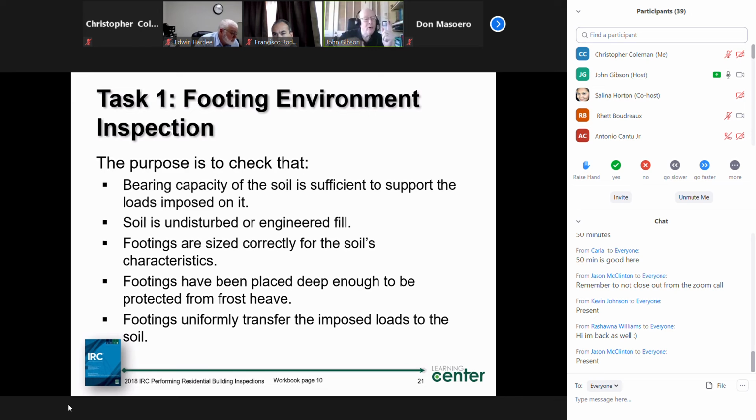And the more points I take, I'm going to have at least 4 of them, 1 for each side. But the more points I take, because if it slopes downhill and I got this swale, I may take a low point up here and a low point down there. The more points I take, I'm going to average those points to come up with what's considered the grade plane.